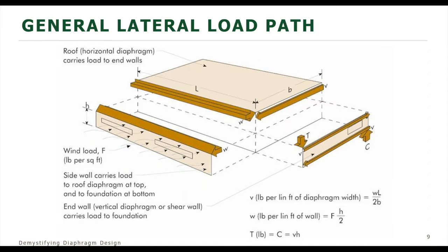And then if we're dealing with seismic loads, we idealize it and say that our mass is concentrated in the diaphragm, sort of like an inverted pendulum, and that load is mass times acceleration, and it's applied at the diaphragm, and that acts like a beam and transfers the load to our shear walls.